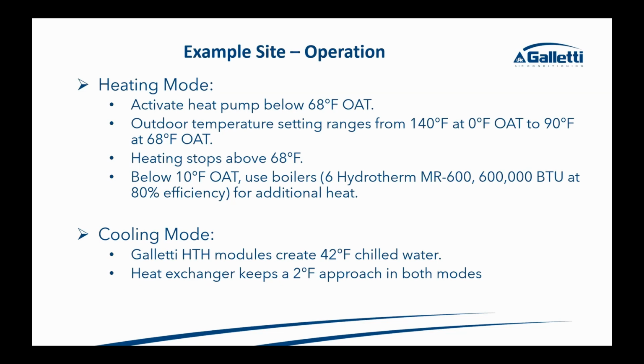So at 10 degrees out, we're able to kick on the boilers, and they're not kicking on the boilers because the heat pump can't keep up with it. They're kicking on the boilers because there is a point where the COP drops off enough, and the efficiency of the electricity on the grid doesn't make a lot of sense. So it's really not a carbon reduction. And then on top of that, the customer is going to pay 3 times as much when you think of the cost of natural gas compared to a COP of 2 or something along those lines.